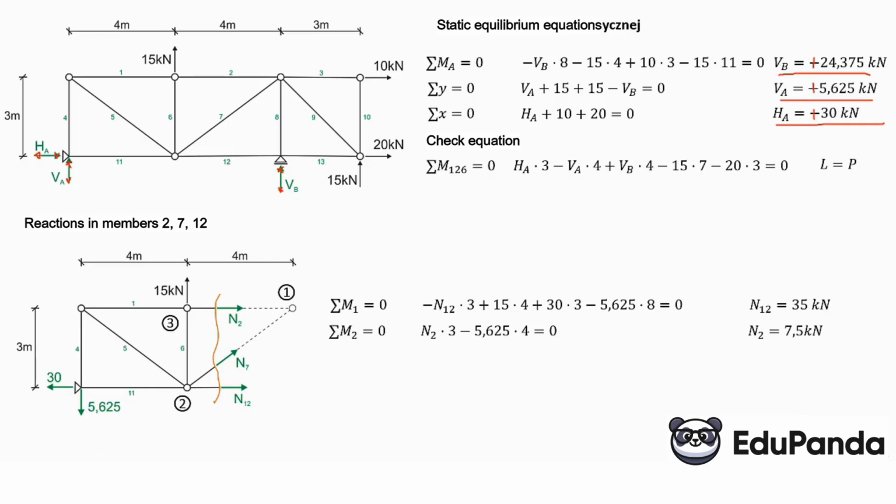And now there's this issue. The reaction N7 is along the entire length of the rod. If someone breaks down N7 as I drew, let's say in the way I did, all right, we are breaking down N7. So here is the vertical component and the horizontal component. And then we would start to wonder at what arm the vertical component acts relative to point 3. And at what arm, in that case, does the horizontal component act relative to point 3? Well, you can get tripped up here too, but you have to be careful, as I mentioned. This reaction N7 is along the entire length of the rod.